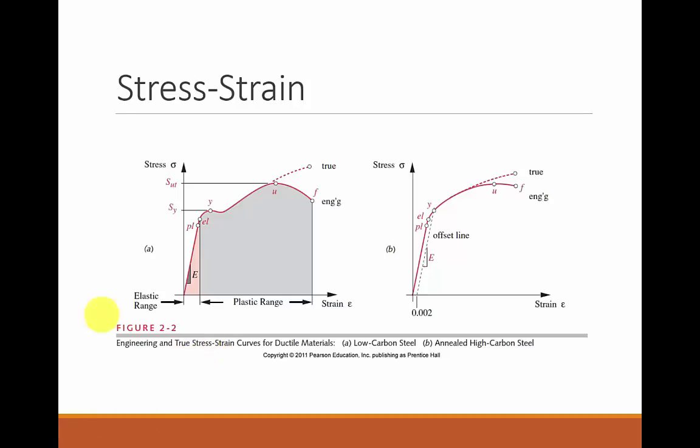The important thing for the moment as we begin this discussion is this whole calculation of E is not valid for an infinite amount of force that we apply to our part. In other words, it's going to stretch linearly for a while, and then it moves into another region, and this region is really defined by the fact that when we remove the force from our part, the part no longer returns to its original position. So for ductile material in the elastic range, if I apply a stress, I'll produce a strain, and then as soon as I quit applying the stress, the strain goes right back to where it was. And that happens as long as the stress doesn't get above some sort of plastic line. It's labeled PL in the graph.